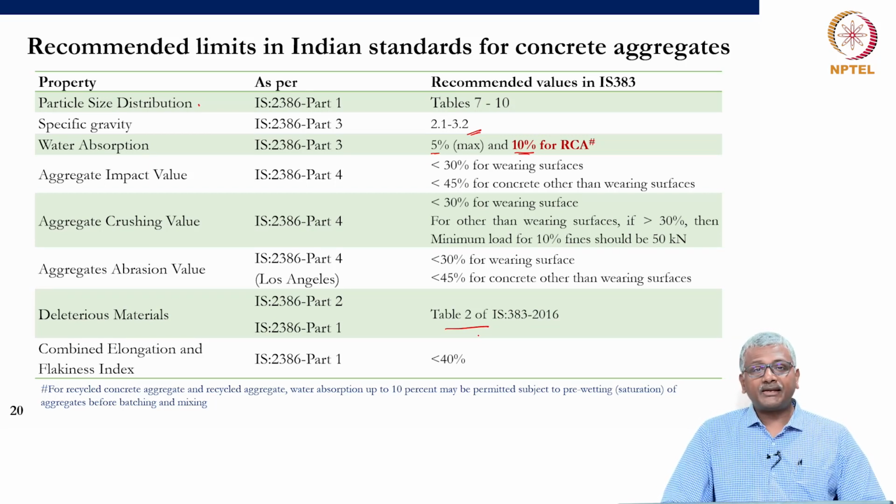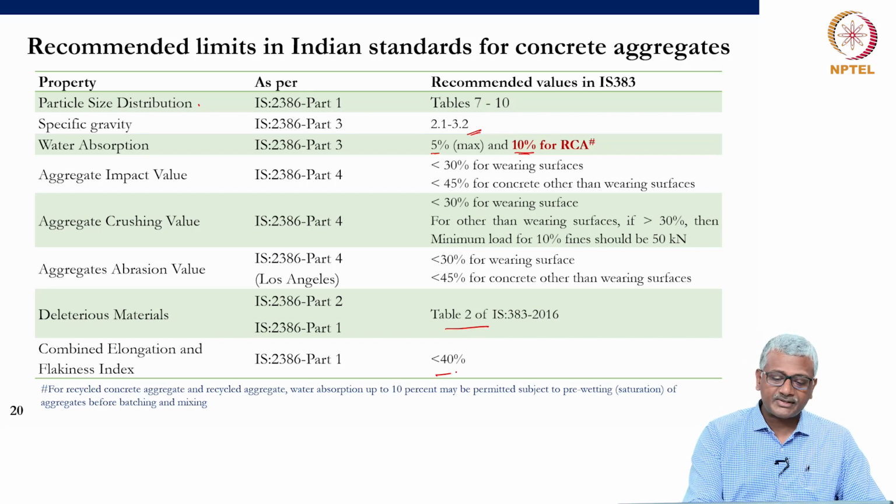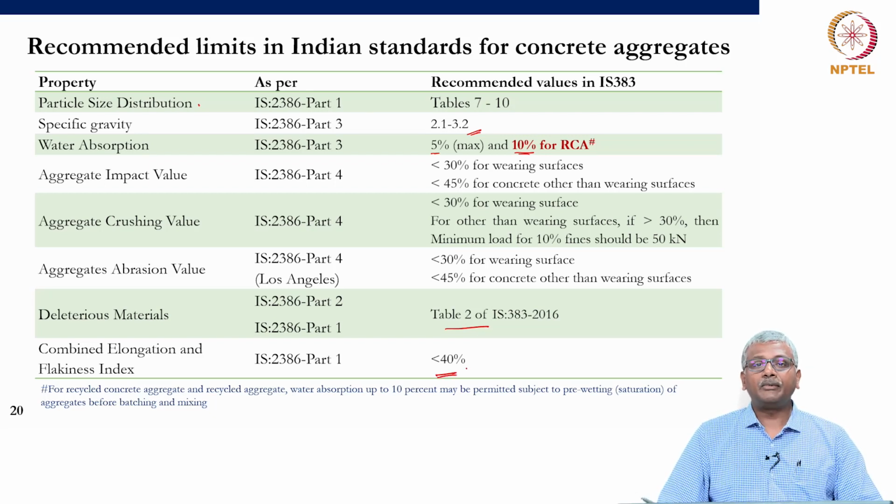Combined flakiness and elongation index, again it needs to satisfy the same less than 40% limit that is described in IS 383.